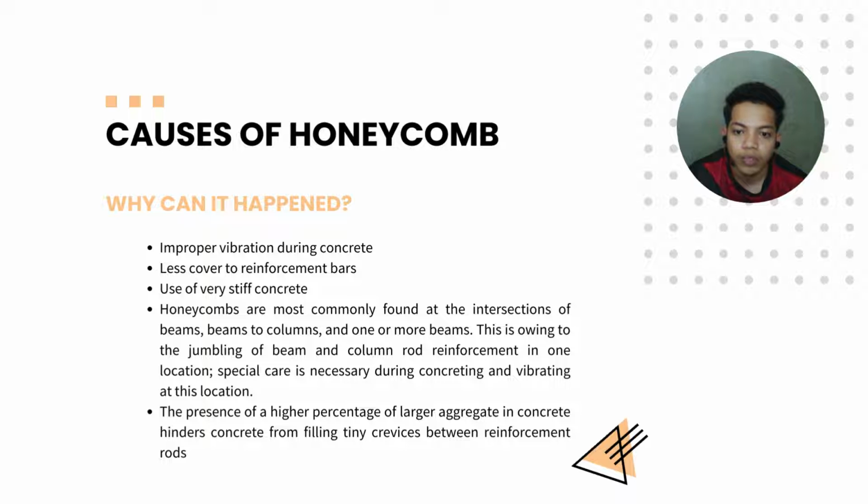This is owing to the jumbling of beam and column reinforcement rods in one location. Special care is necessary during concreting and vibrating at this location. The presence of a higher percentage of larger aggregate in concrete hinders concrete from filling tiny crevices between reinforcement rods.